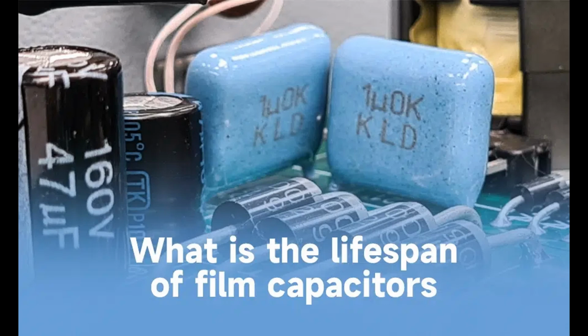3. High cost. More expensive. Film capacitors are typically more expensive than electrolytic and ceramic capacitors, especially at higher voltage and capacitance ratings. The materials used, such as polypropylene or polyester, and the complex manufacturing processes contribute to their higher cost. In applications where cost is a key factor, film capacitors may not be the most economical choice.